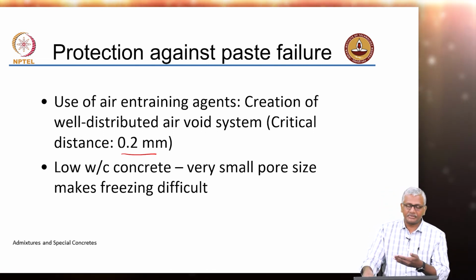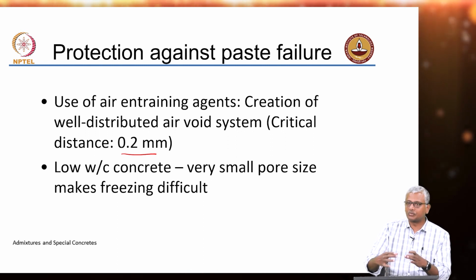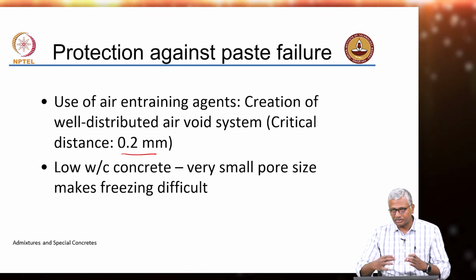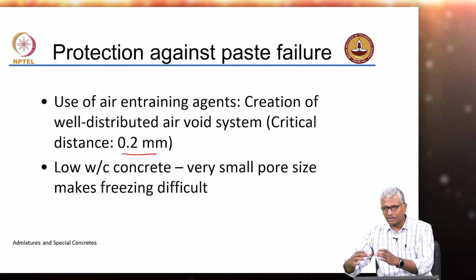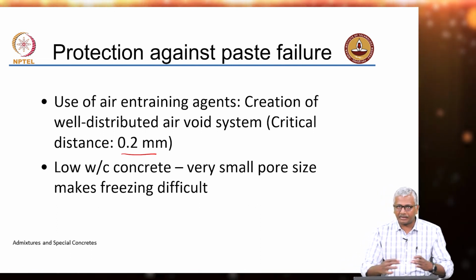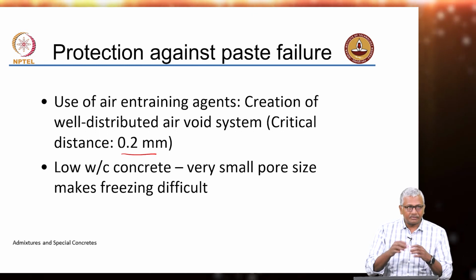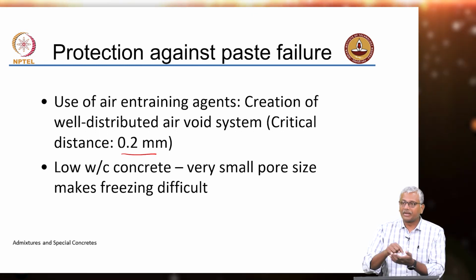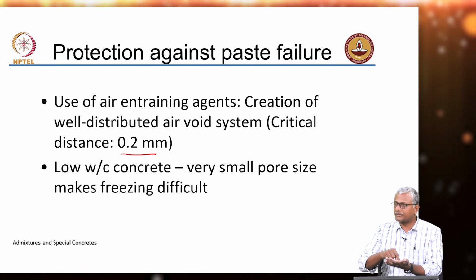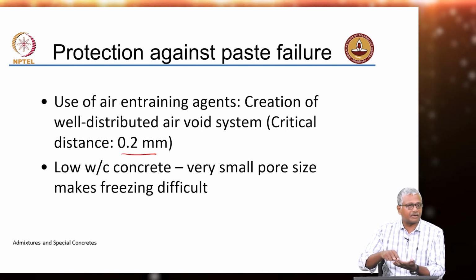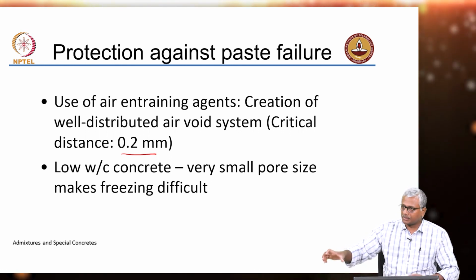And then what happens is you have a stage which is moving in the x and y direction. So, you traverse in the x direction first, and then you come down to the next line in the y direction and then traverse again. Each time that you traverse, when you are viewing under the microscope, the crosshair of the microscope comes and rests on some object in your concrete, either on a coarse aggregate or on fine aggregate or an air void. So, there is a counter.